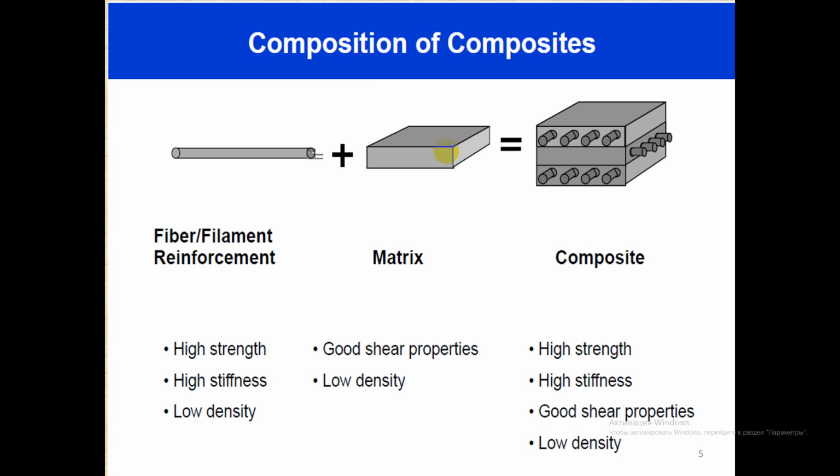In addition, both the material and the geometric properties can be adapted for a specific application. Several materials are available for the fibers, that is glass, aramid, carbon. Therefore, fiber reinforced polymer with carbon fibers is abbreviated as carbon fiber reinforced polymer.